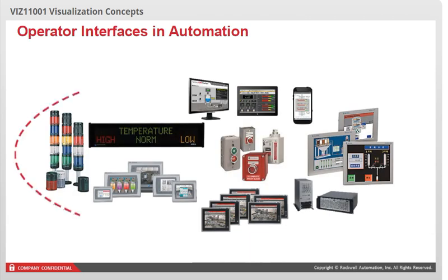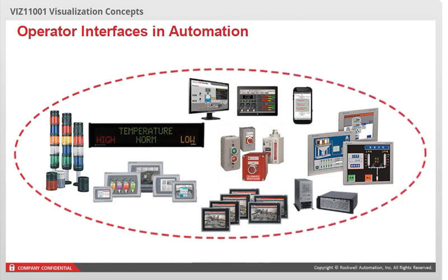All of these devices provide the operator the means to visualize a process. Selecting the right solution depends on functionality, cost, location, certification required, amount of information required to view and control, as well as the existing infrastructure at the customer site. As we saw earlier, these interfaces can reside on the machine, in the control room, and/or distributed throughout the process line.